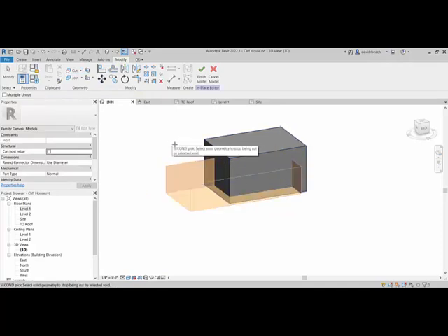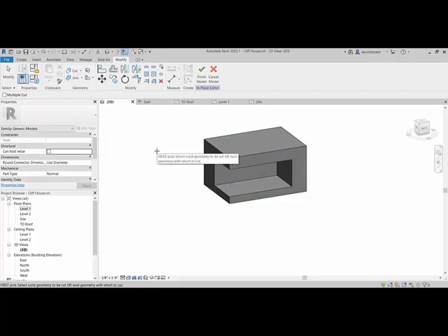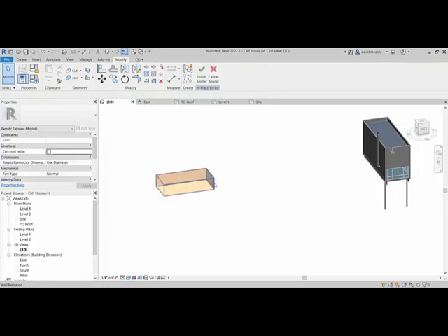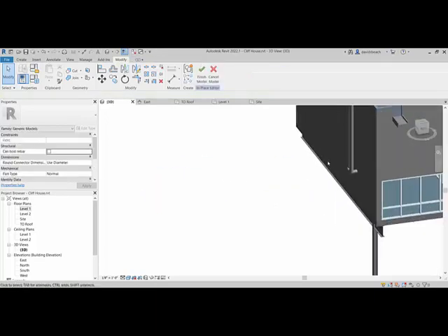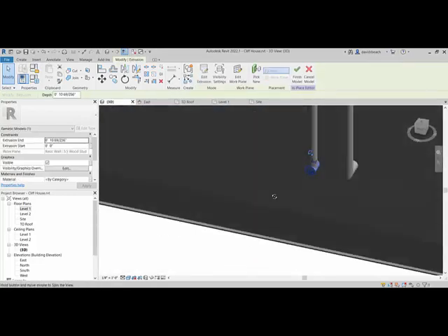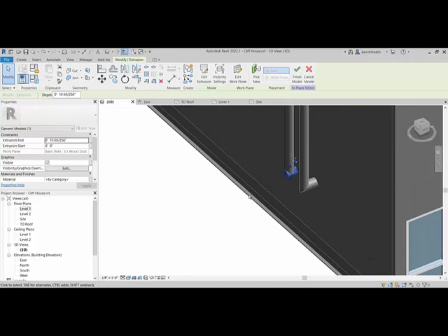Every now and then Revit won't cut something. And when that happens, so you can see I've got my void form here, it is not cutting this. I can always activate cut. This cuts that, right? I can also say I don't want this to cut that. There's a whole sort of time when you're modeling things that sometimes as you're building up a fairly complicated object, you need to be able to manage those. So I'm going to delete both of those. And let's dive into voiding those two pieces off.